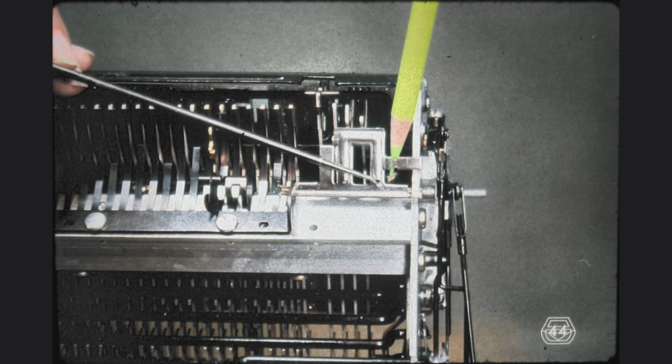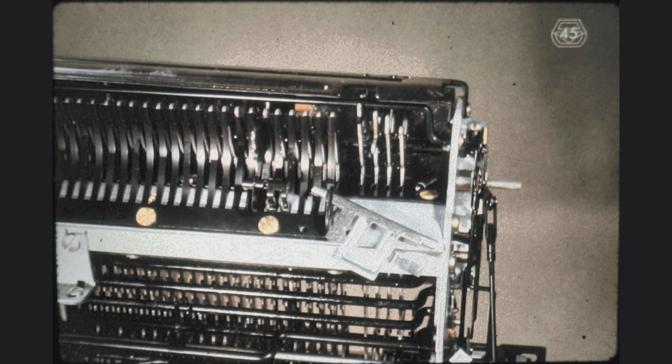This spring holds up the repeat stop bail. As our first step, let us remove this spring. Next, we unhook the indicated restoring spring, also called the spacebar return spring. By rotating the repeat stop plate top to the front, as shown, it becomes possible to extract it from the machine by first sliding it slightly toward the left.